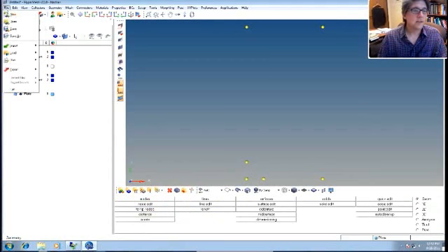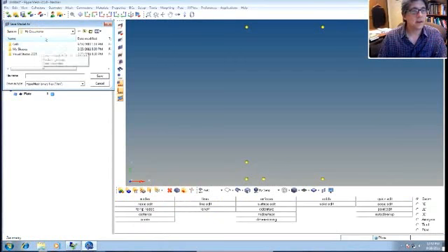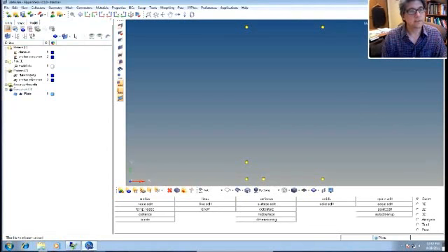You should probably save this every now and again. So we could do save, and this will just save as a Hypermesh file. This really isn't something that Nastran or any other solver can read. It's something that Hypermesh reads, and it has other information in it. You can then, from that file, export to whatever solver you want. So we'll save that as just plate.hm. So that's a Hypermesh file. It contains all this stuff. You can exit and load that up again.